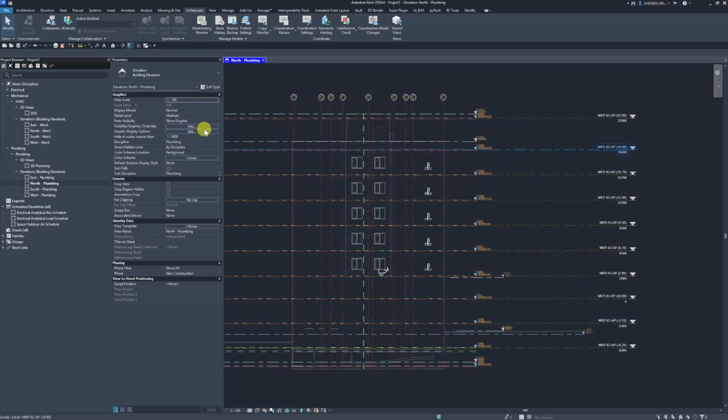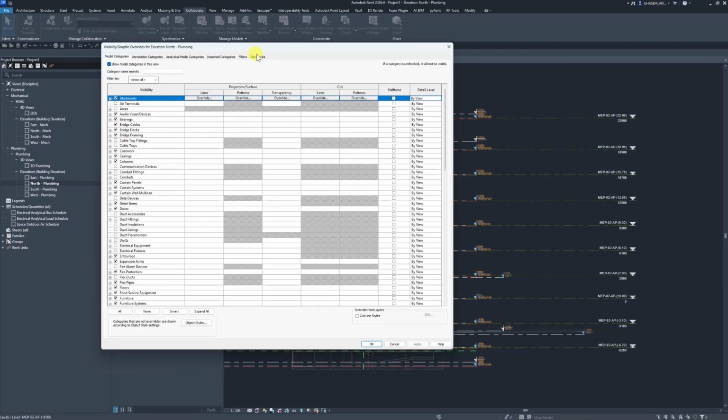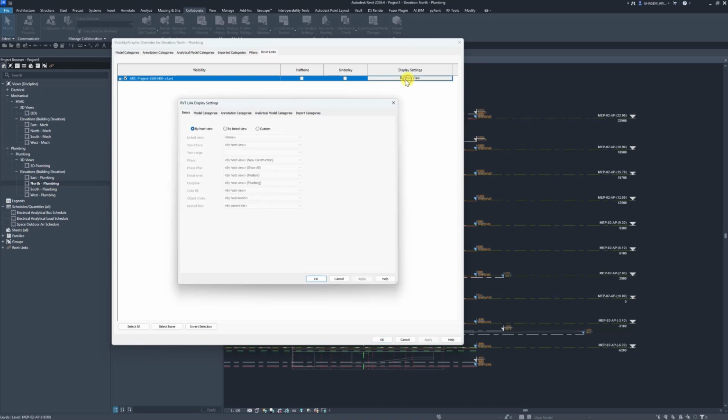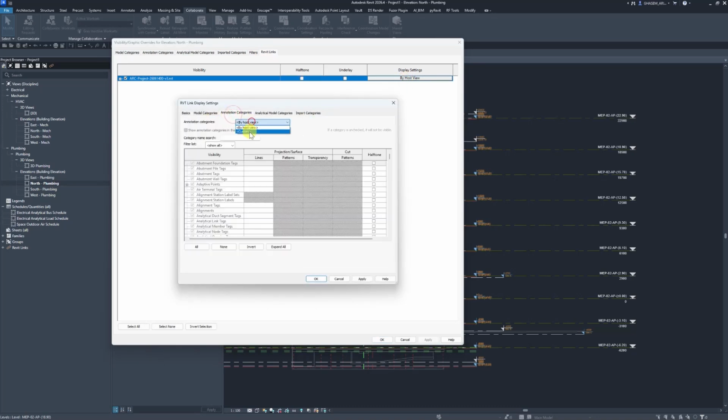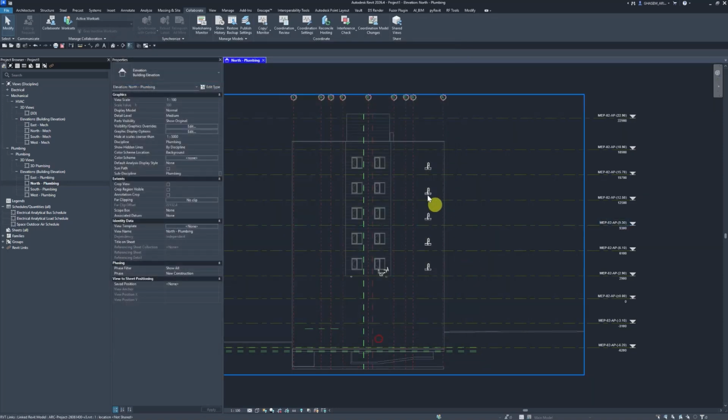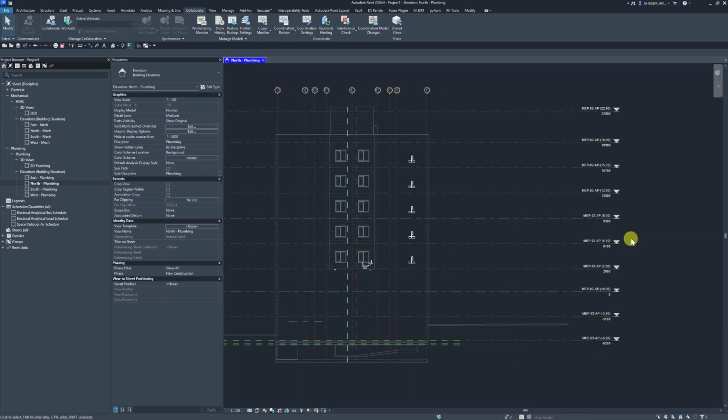And regarding the viewport, guys, it's a bit crowded, so let's change that. Opening VG from Revit links by host, select custom here as well, and now we can turn off the levels. Now let's check the viewport again. See, this is way better. Anyway, as I said, these are reference levels.